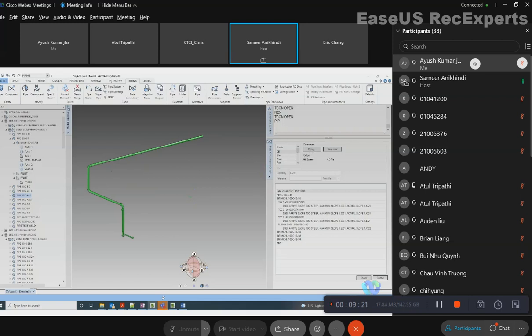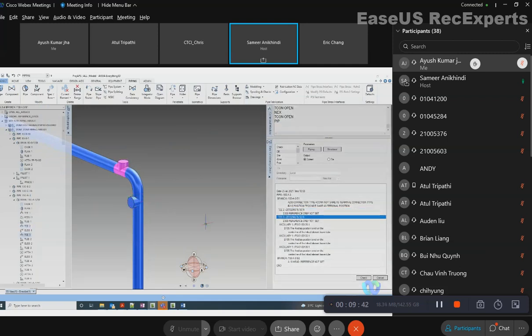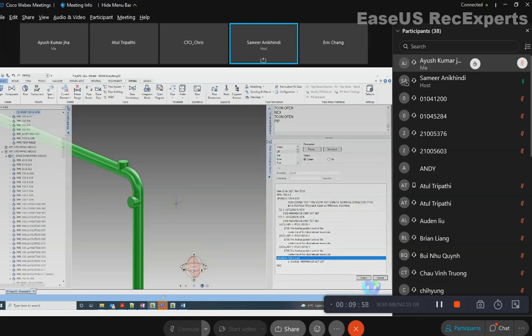Check C. So a couple of problems here. For T, let's see, still no connection reference over here. So of course, if there is no reference required, why has the T been modeled? So all these Ts, no branch connected over here. Ancillary. Okay, this is support. We have not done support. Leave it. When we do supports, we'll discuss it. Head reference is not set. So here for this branch,